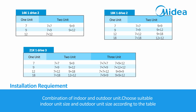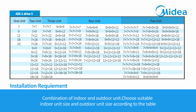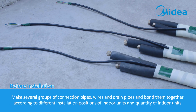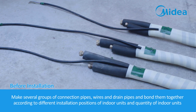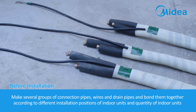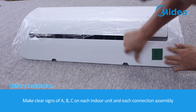Combination of indoor and outdoor unit. Choose suitable indoor unit size and outdoor unit size according to the table. Before installation, make several groups of connection pipes, wires, and drain pipes and bond them together according to different installation positions of indoor units and quantity of indoor units. Make clear signs of A, B, C on each indoor unit and each connection assembly.